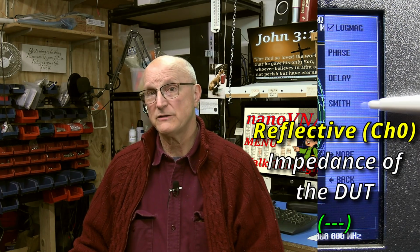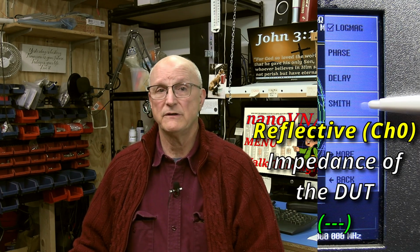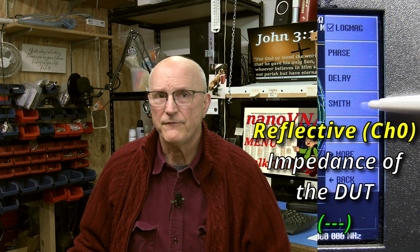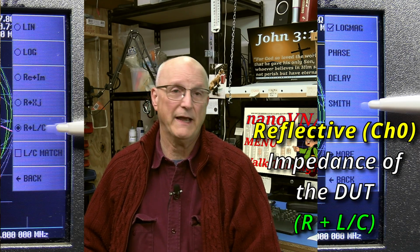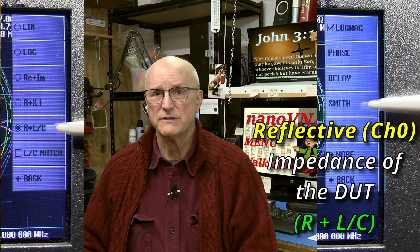Well, the next option is the Smith option. What you see here depends on how you set up your markers. To access the format options for the values shown on the Smith chart, you have to go all the way back to the main menu, then tap on the Markers option, and then the Smith Values option. In reflective mode, the Smith format is where we go to measure the impedance of a given device under test. By default, the nanoVNA displays the impedance as resistance plus capacitance or inductance when a marker is defined.